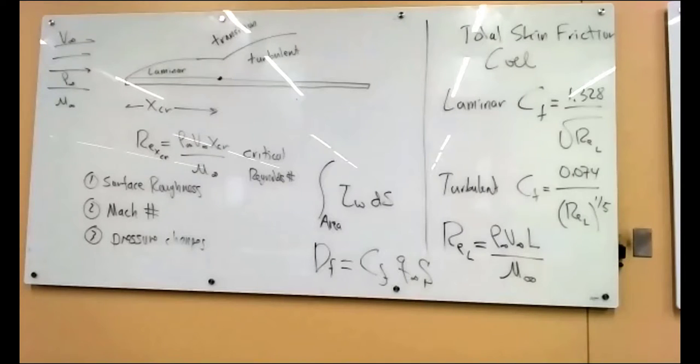And so that's why, talking earlier, they just tried to design aircraft wings that maintain laminar flow over the entire wing because it has less drag. So they thought that was good. Makes sense, right? Less drag, less fuel required.